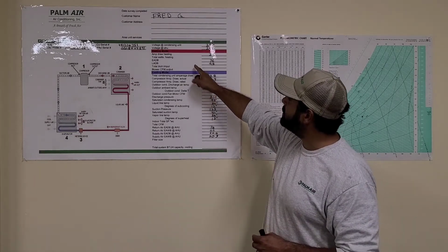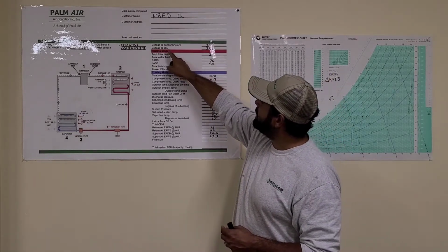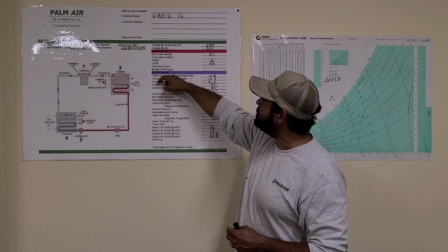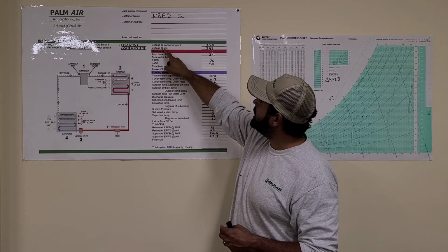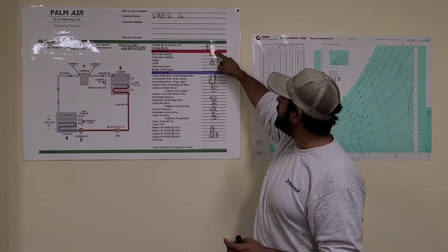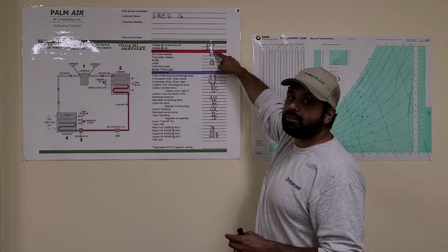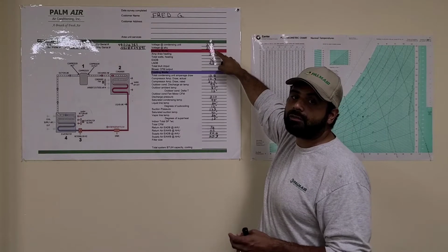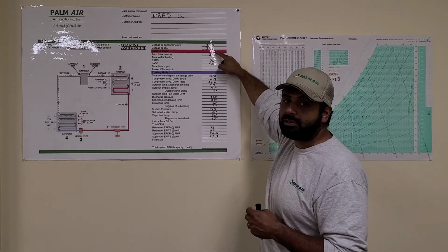In this case, the first thing we need to do is find out how many watts we're actually using in the heating mode. So we take voltage at the air handler, which you can see here. It's kind of small on the camera, but it's 247 volts. That's a little high for residential, but we do see that number quite often, especially as we get further out west here in South Florida.